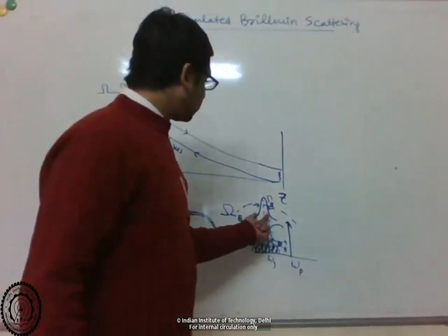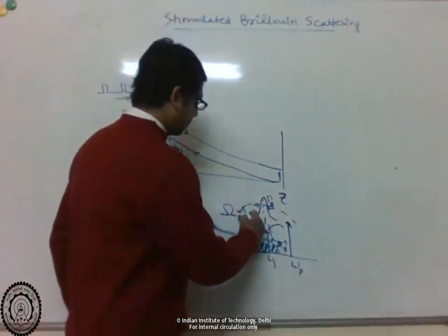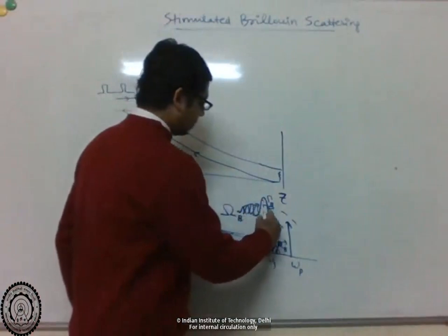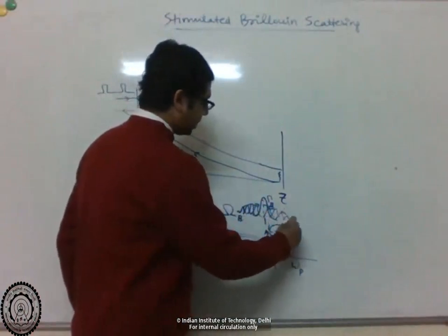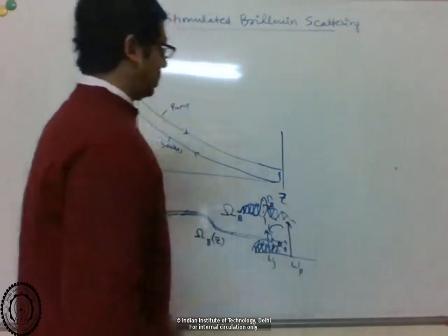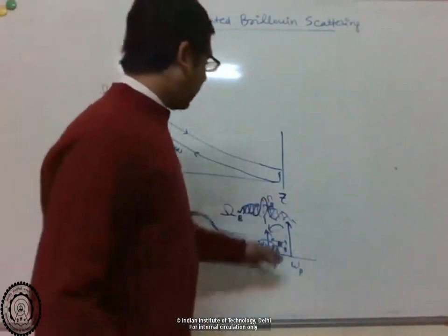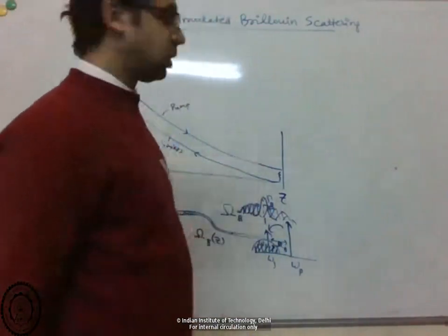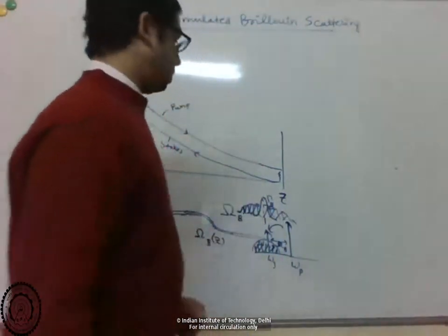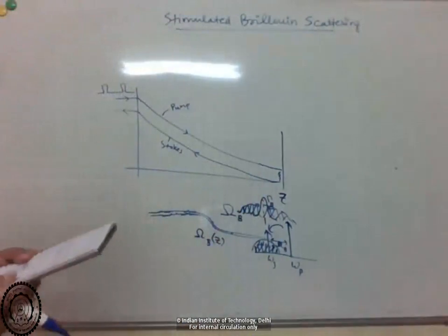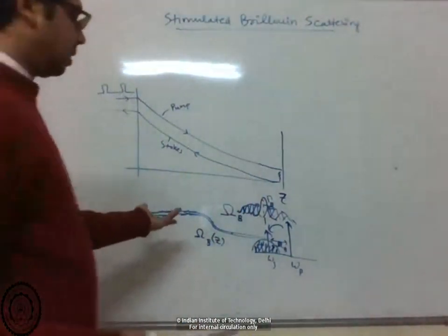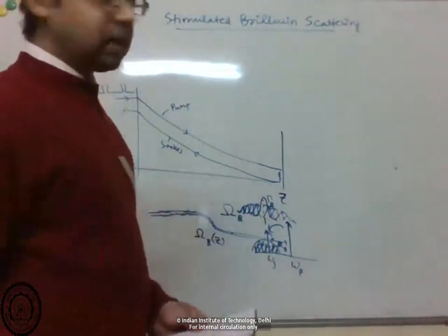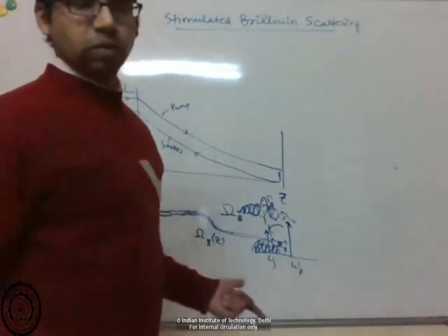So basically what you're doing is adding different gain resonances here at different frequencies, artificially broadening the line width, and if you broaden the line width, the peak gain goes down. Right? So basically you can think of it like that. So fiber inhomogeneity is helped, but as the fibers became better and better, then the Brillouin scattering also got worse.